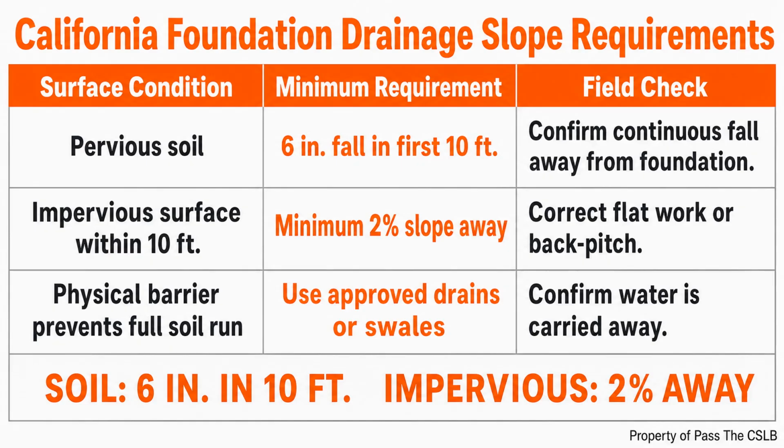This matters during survey and layout coordination because control points often sit close to changing excavation conditions. A crew may be focused on saving a string line while a ramp, changing surface condition, or underground conflict creates a more immediate hazard. The competent person has to be able to stop the operation and correct the condition. The contractor's best coordination happens before production pressure takes over.